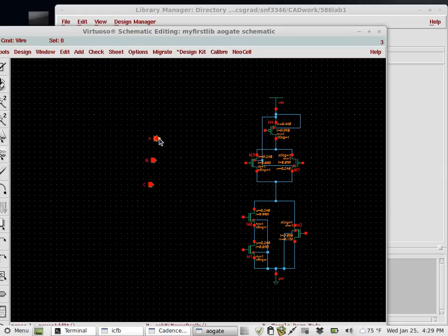Again, I just press W to make wires. How do 480 plus 480 give us 240 at the end? It's because the equivalent resistance is equal to 240, which is equivalent to a transistor with 240. Remember the width: if it's in series, then the resistances add up, so it's like you have a transistor with half the width. It's equivalent to that. You can verify it later.